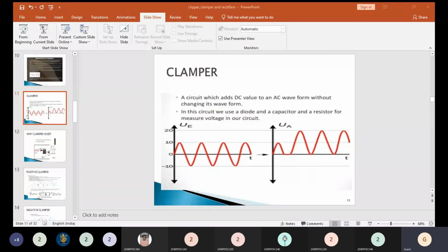This is not Vout, this is Vi. So what happened to your input voltage Vi? Vi will definitely be greater than 2 voltage. It's not only 2, we also have the basic breakdown voltage of a diode, 0.7. Silicon type of diode we are using, so we are getting 0.7. So 0.7 plus 2, what happened? 2.7 voltage. So Vi is greater than 2.7 voltage.